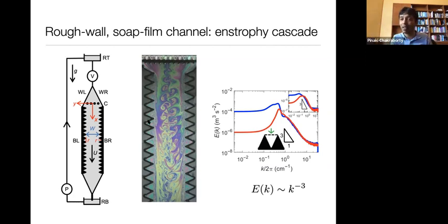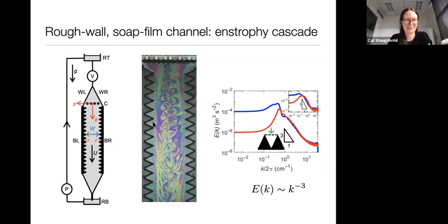So we switch technique and use PIV, where we can get velocity fields. Now, with LDV you're dealing with a beam, but with PIV, you're dealing with a laser sheet. And reflections and all kinds of other complications of introducing the sheet with respect to a beam are significantly harder. And that's the technical reason why doing the experiments for the rough channel is harder than for the smooth channel. It took us many years to get this working right. Yeah. Oh, that's so interesting. Thank you for answering my question.